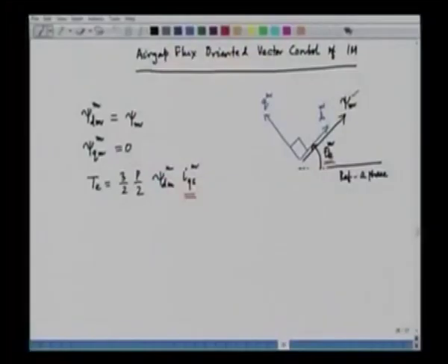But we have actually seen in the last lecture, in fact, we have already derived this equation, and we have seen that when we change the torque by changing i q s, the flux is also changed. So, in fact, psi d m and i q s in the air gap flux reference frame are coupled. They are not decoupled variables; although the two are in two different axes, they are mutually coupled. If we want to change i q s, psi d m is affected. So, we will just rewrite the equation that we have derived in the last lecture.